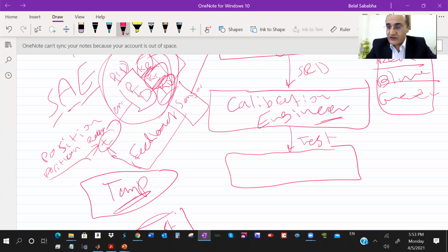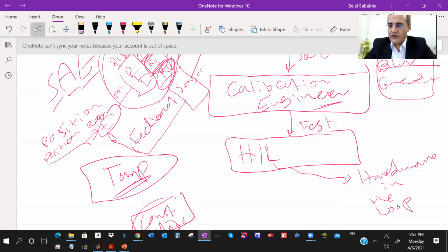In some industries, we used to do this on HIL. HIL is for hardware in the loop. Hardware in the loop, software in the loop, where if it's difficult to simulate a piece of hardware, you can use it in a simulation environment, still using hardware and testing. So in automotive, for example, we used to have something simulating a car. So you sit in front of a computer and you start driving and monitoring everything. So there are HIL engineers who design your simulators. But afterwards, something to bring you to reality, afterwards you can do it on the actual hardware.